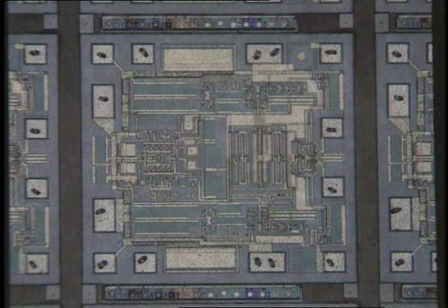Here, illustrative of the high-speed capabilities of translinear multipliers, is the 8834, which was introduced about 2 years ago. It has a bandwidth at the chip level of about 1 gigahertz, although in fact the useful frequency range is limited by the package to perhaps 500 megahertz. At the recent International Solid-State Circuits Conference, many companies were reporting translinear multipliers with frequency ranges up to several gigahertz using recent technologies.